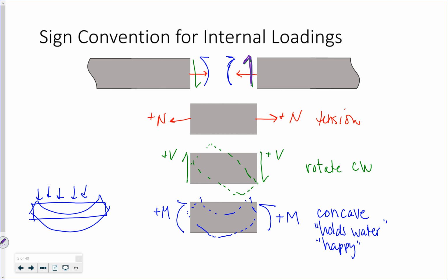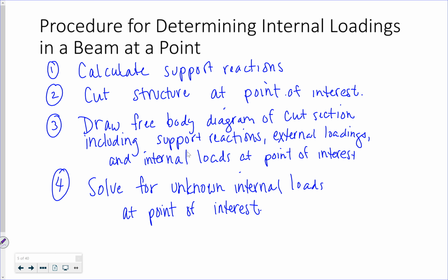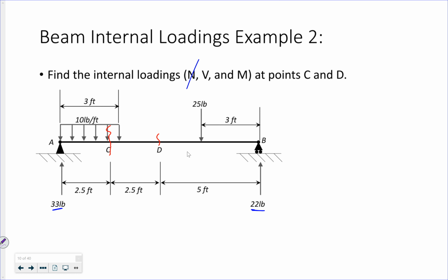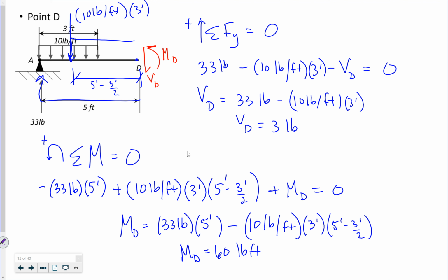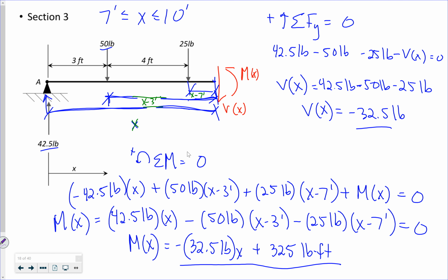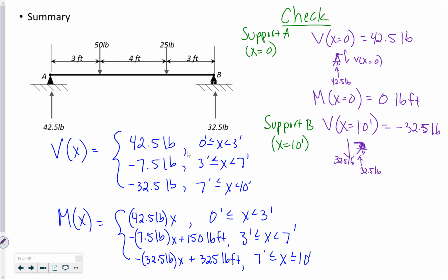If I'm looking at the right side from the support, down is positive if I'm looking from the support this way. Up is positive if I'm looking from the support that way. So that is why it is negative and is acting downwards, not simply because it is acting downwards. I want you to take a minute and think about that.